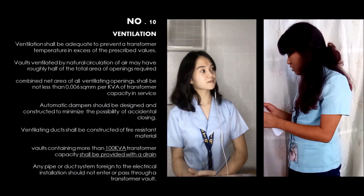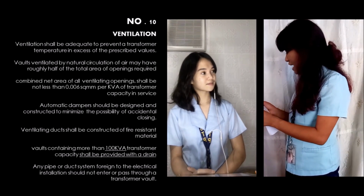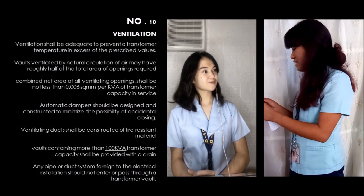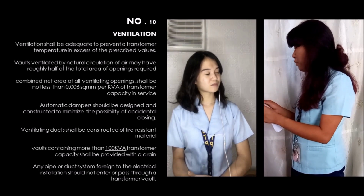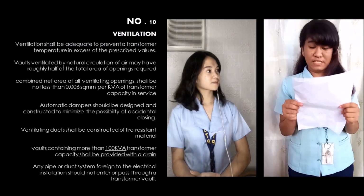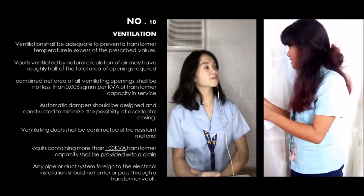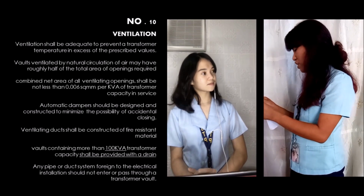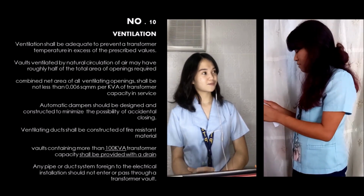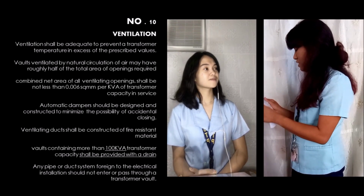Vaults ventilated by natural circulation of air may have roughly half of the total area of opening required. The combined net area of all the ventilating openings shall not be less than 0.006 square meters per kVA of transformer capacity in service. Automatic dampers should be designed and constructed to minimize the possibility of accidental closing. Ventilating ducts shall be constructed of fire-resistant materials.